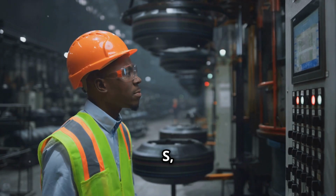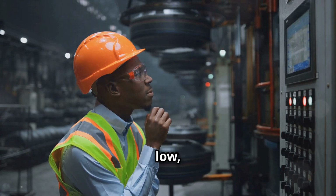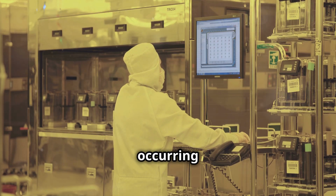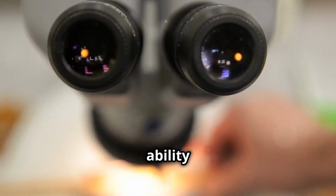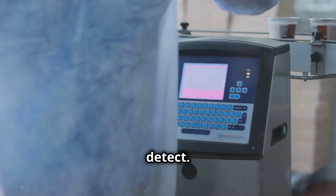Severity, or S, is a rating of how serious the effect of the failure would be, typically on a scale from 1, which is low, to 10, which is high. Occurrence, or O, is the likelihood of the failure occurring during the process, rated from 1, unlikely, to 10, frequent. Detection, or D, is the ability to detect the failure before it causes a defect, rated on a scale of 1, very likely to detect, to 10, unlikely to detect.